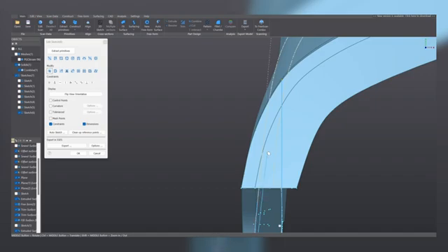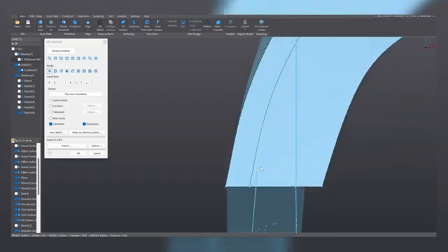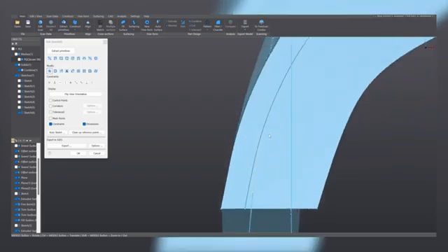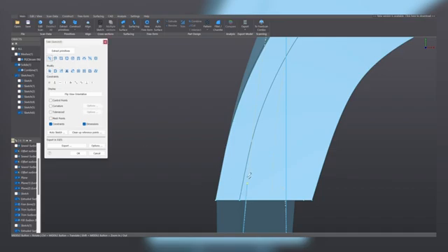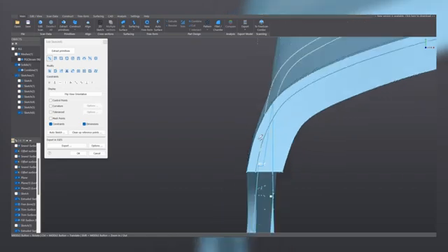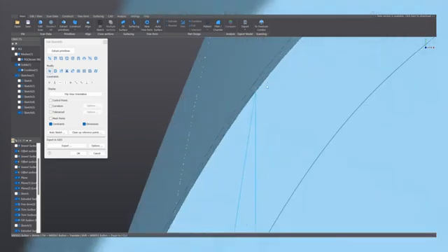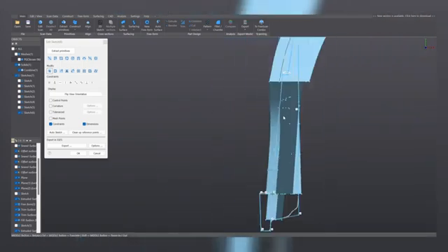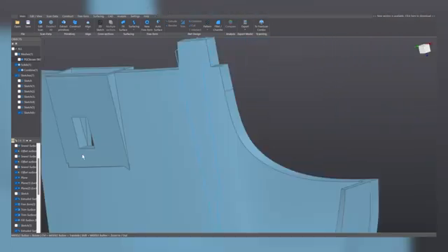And let's also extend this other one, but paying attention not to go beyond the geometry of the original object. So we are going to move a little bit to the inside and then connect the two endpoints. Here I can see that they appear orange, so let's make sure they are connected. Now this is a closed sketch.